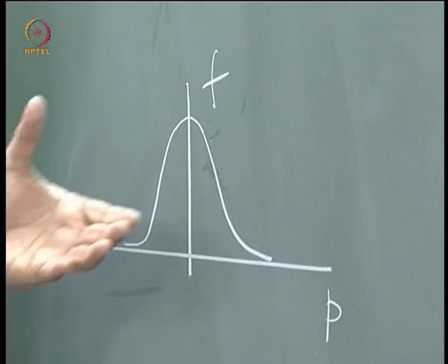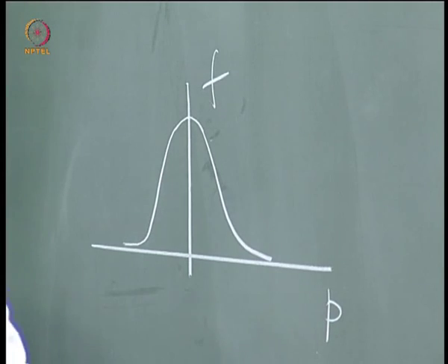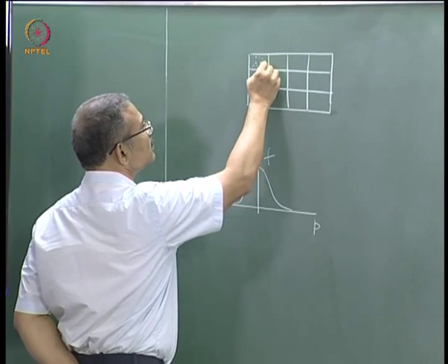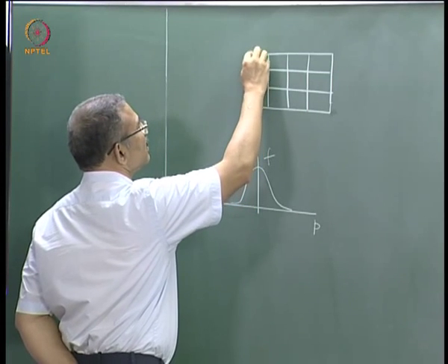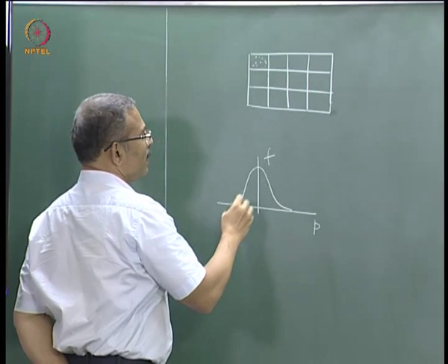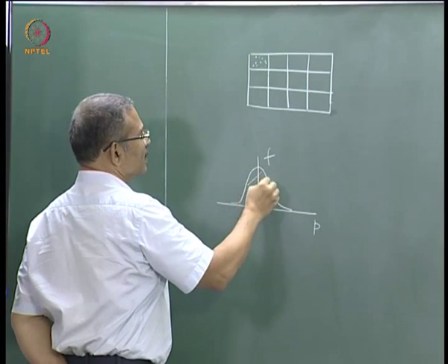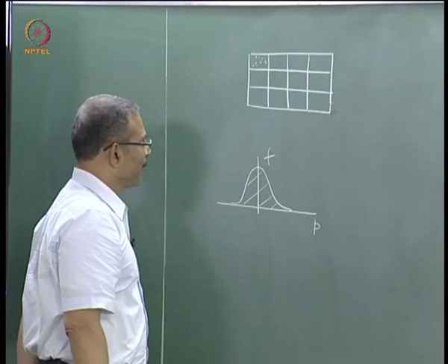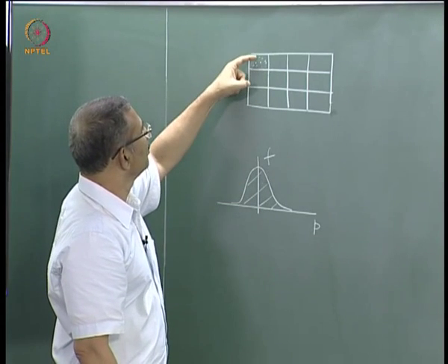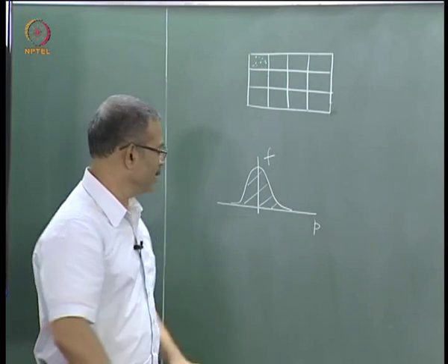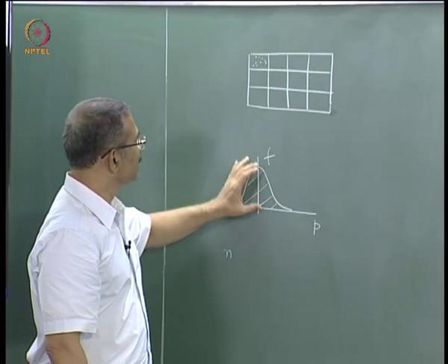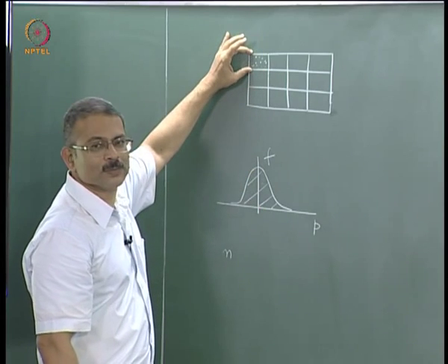For example, in terms of the distribution function, if I want to know the number of carriers, then I can take this local volume. I will find that whatever electrons are there in this, they will all be distributed like this. So if I take the area under this curve and divide this area by the local volume, then I will get the carrier concentration n. Just the area under this curve will tell me the number of carriers in this local volume.